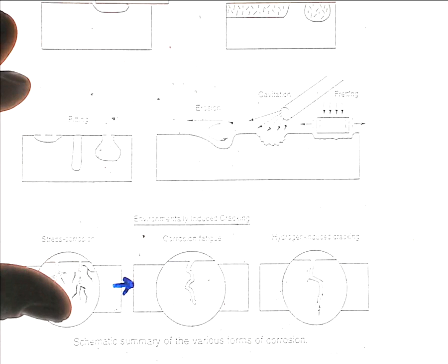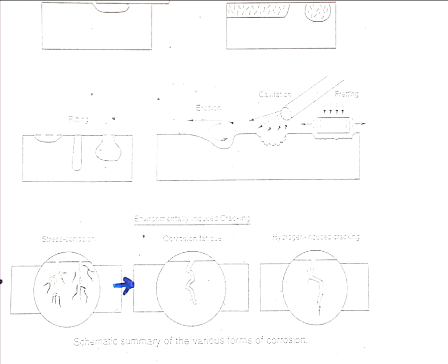And we whizzed through and looked at the effect of fluid flow, to say initially you get refreshment in systems which increase the corrosion, because you've got an electrode surface or an anode surface, and you want reactants to go to that surface and react to produce metal ions, and you want those metal ions to be washed away from that surface afterwards.